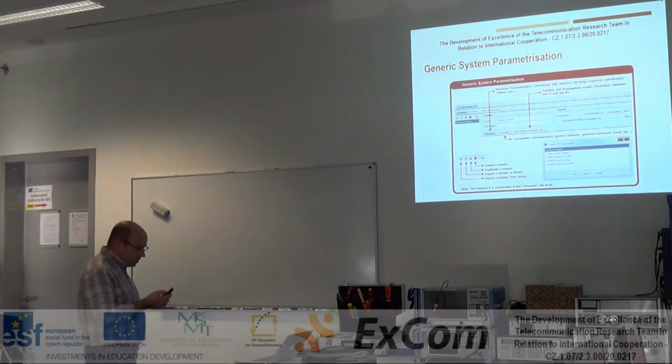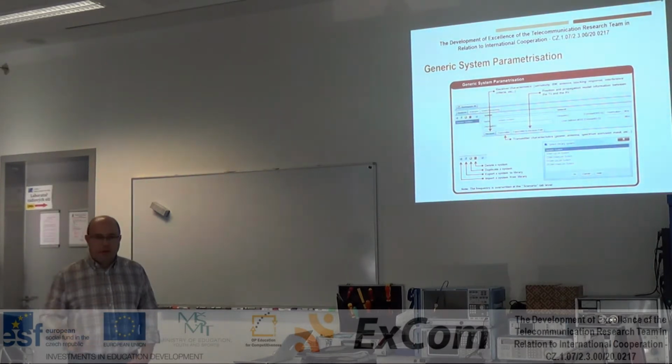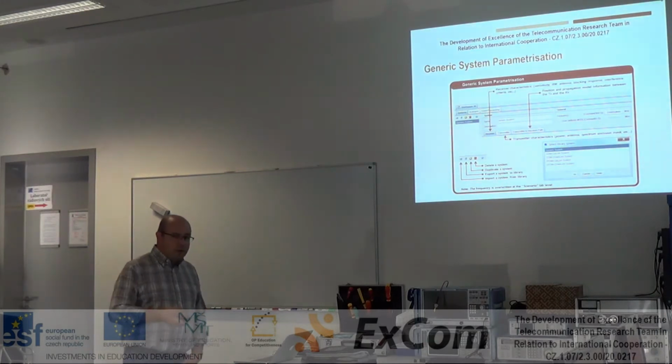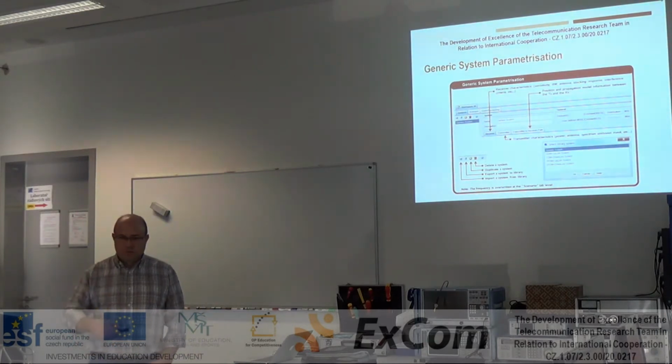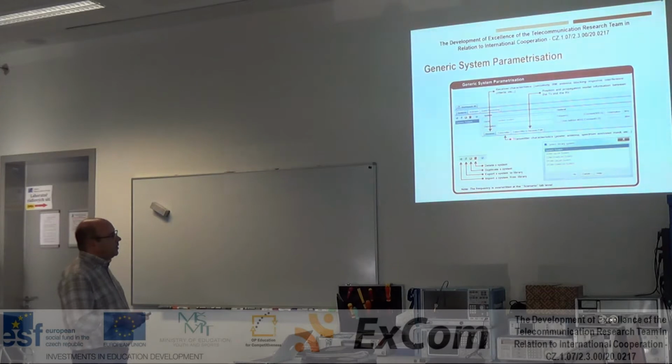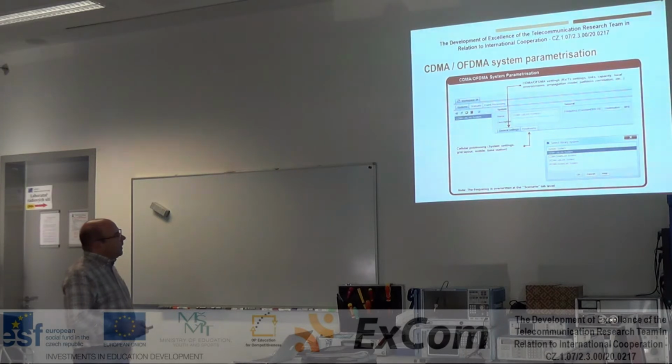Here on the receiver and on the transmitter, you have to define all the properties: power, antennas, and so on. Then you have to define the path between the transmitter and the receiver. SEAMCAT has maybe 20 propagation models already defined, from ITU and other organizations. And by the way, free space, the simplest one, is also there. So the systems are actually the transmitter, the receiver, and the path between them.